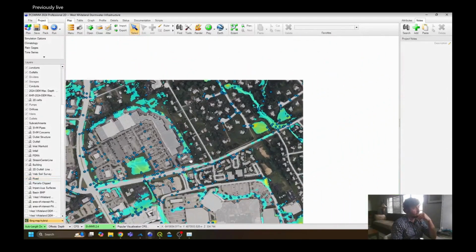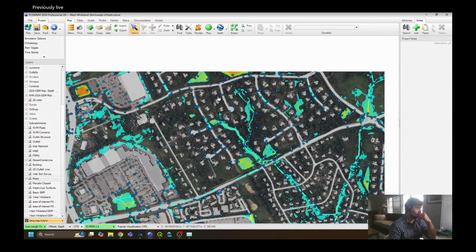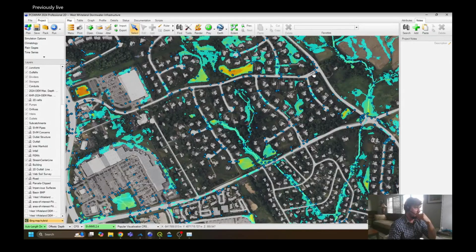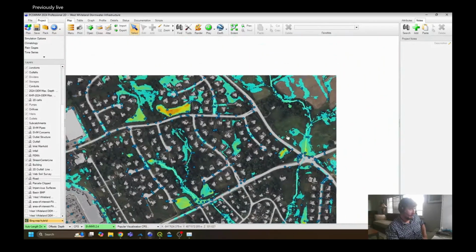Okay, here we go. So I have a road polygon. This one came from the municipality, but if I don't have this, it's pretty easy to get street center lines. And I can use a buffer on that center line and say, hey, buffer out like 15 feet in either direction. So I have a polygon for the roads.